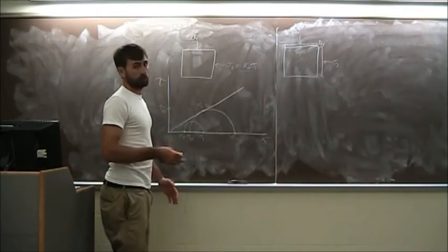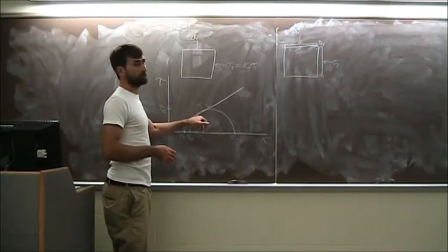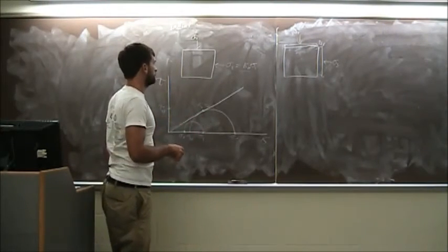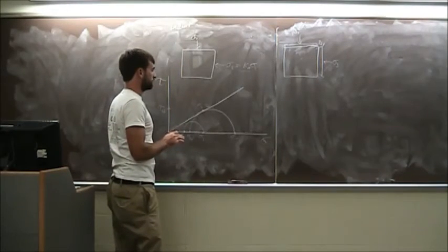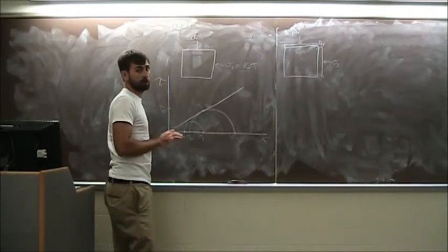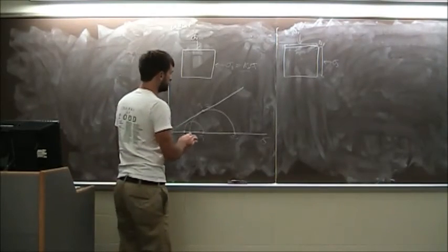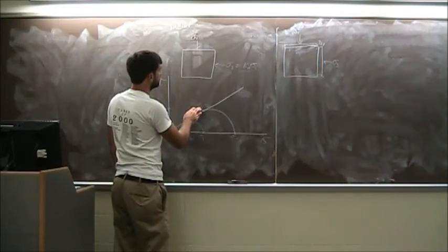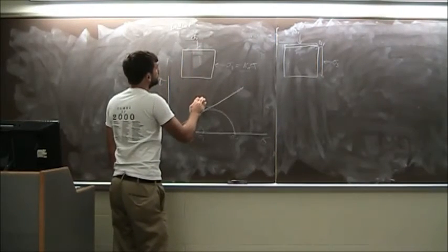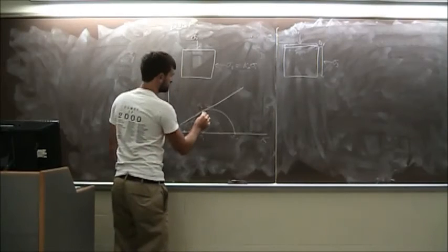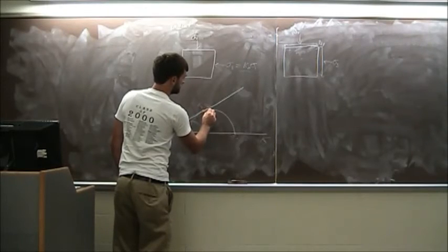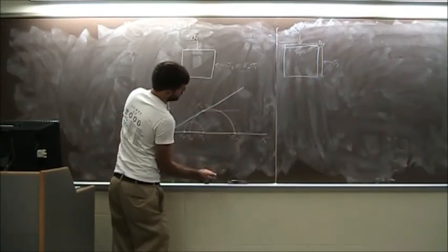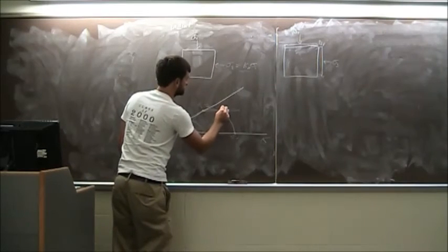But we need to figure out how they rotate. So we need to figure out where the pole of this Mohr circle is. So we know that the pole is the point where all stresses in the planes they act on intersect the Mohr circle. So we know that this sigma 1, which hasn't changed yet, is acting on the horizontal plane. So where this intersects the Mohr circle is the location of the pole. So we have a point here, draw a horizontal line, and it intersects right here. So that's your pole.